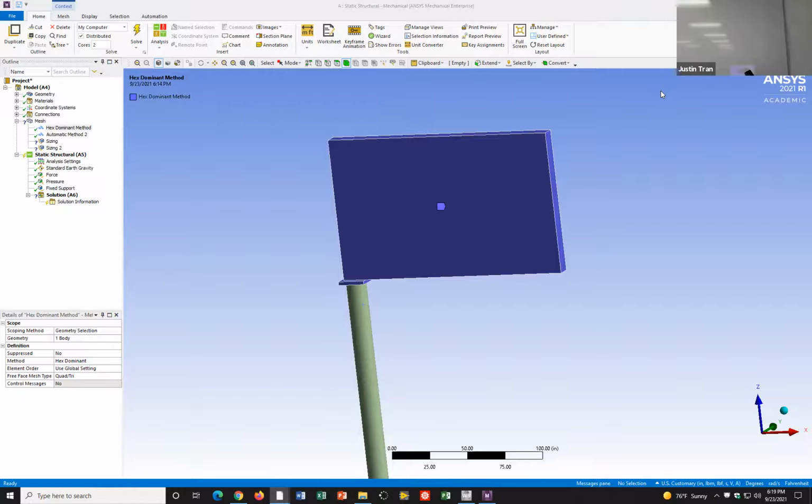So I would suggest you run the simulations first. Typically you would want a finer mesh or smaller element size where you see higher stresses. So wherever your high stresses are, that's where you want to have smaller elements. This area over here, like the circle one, will probably fail because of the wind over here and the weight. So this would be our issue, maybe the point of failure. Run the simulation first, and then you can see.